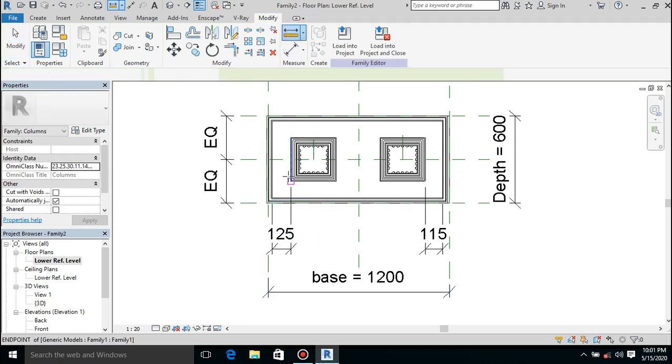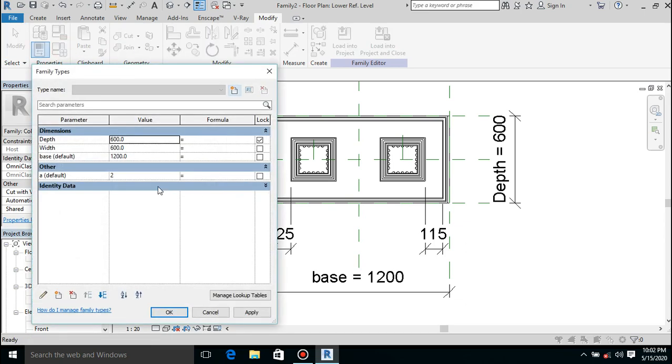Nice. So I want the distance between this to this to be applicable. So I want from here all the way to this place, which is about 595. All right, 595 is okay, but not totally okay. If you're going to array it, the distance will reduce. I don't know if you understand what I mean. So instead of from here to here, let's make it from here to this place, which is 450. Here is the parameter we created, this and this.